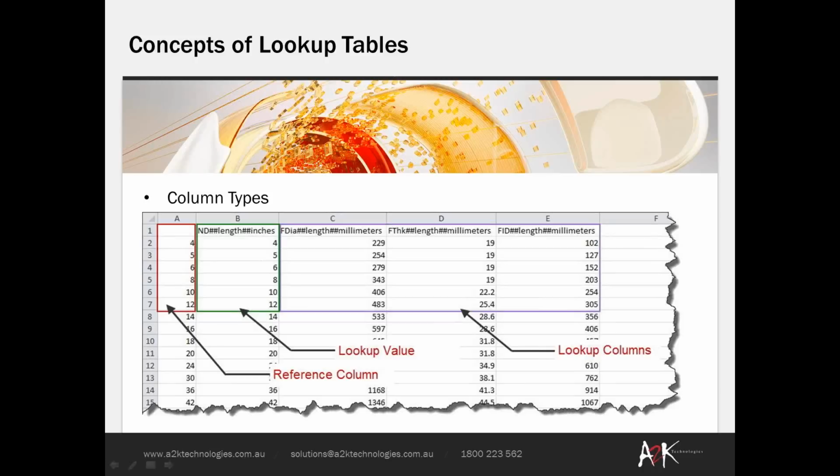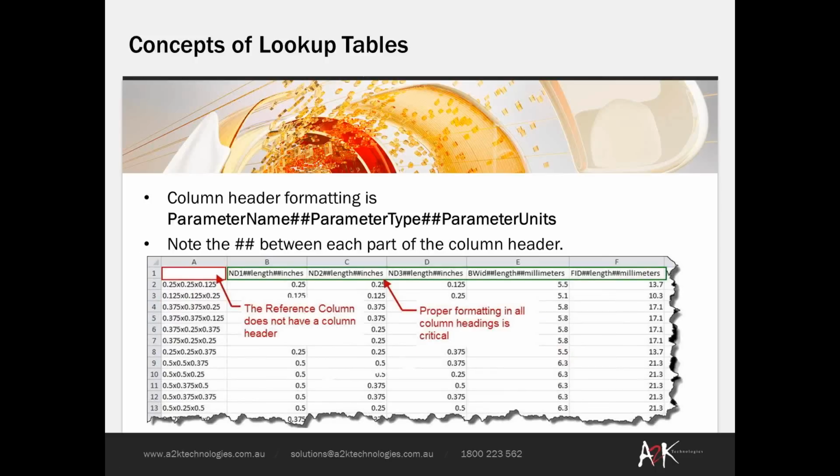Okay. So we'll come across to the next slide here. All right. So there's a little bit to be understood about the formatting of your lookup tables. The top row is referred to as the header, and as I mentioned, the reference column does not have a header. It's left blank. You can see in this example, as I mentioned, the reference can be whatever the user desires. They've put some size references there, but again it has no bearing on the use of the values in the project or in the family itself.